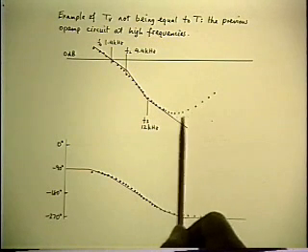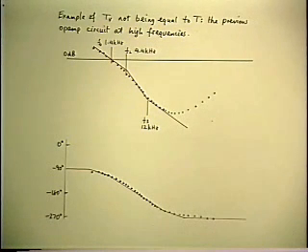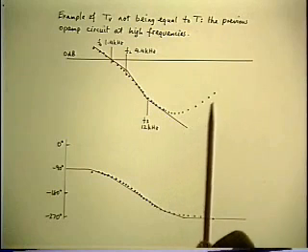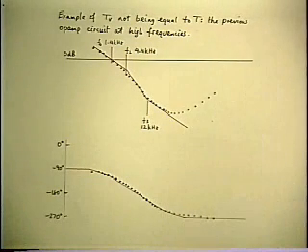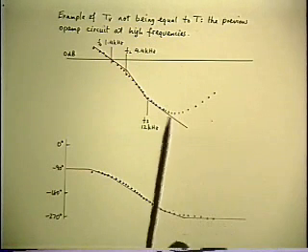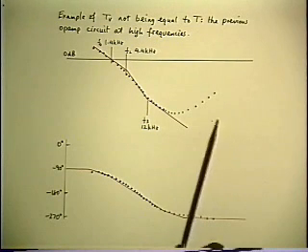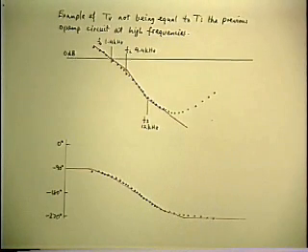For one thing, if you get measurements of loop gain that do this, it's not too likely that the loop gain really does that. Because we haven't seen any op-amps whose gain turn around and come back up at very high frequencies. In fact, we'd be very happy if someone could give us one of those. So it's not likely that the loop gain really is doing that. And so we'd better check into the other possibility that we're not measuring what we think we're measuring.